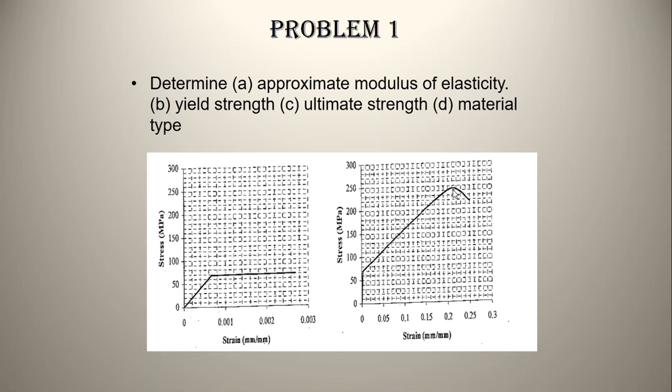So these are the two things that confirm it. And the last one is that the ultimate strength we found is 245. For this particular copper alloy, it is the closest. We have E as 101, yield stress as 70, and ultimate strength given here is 241. Our graph is approximate and we still read close to that 245.